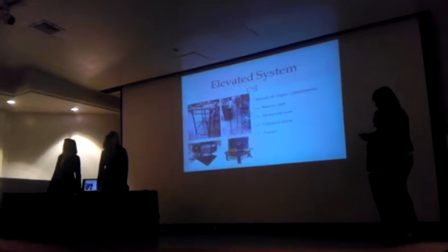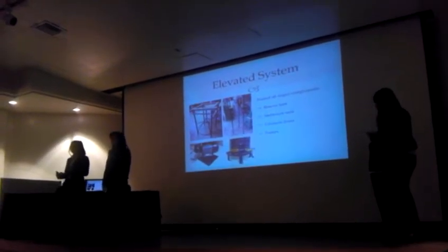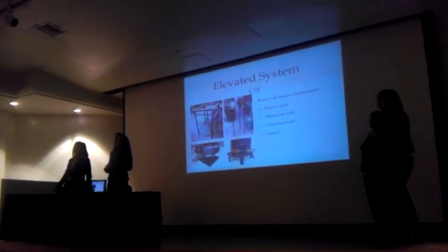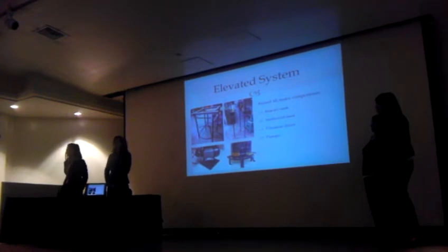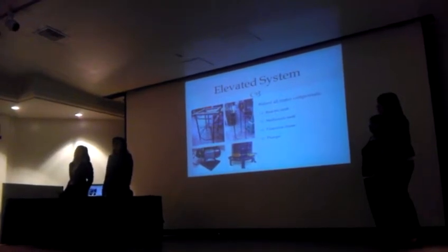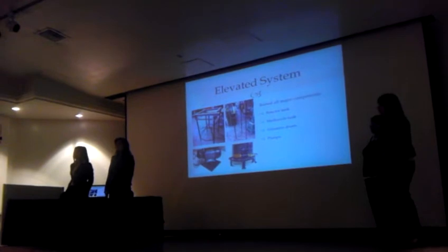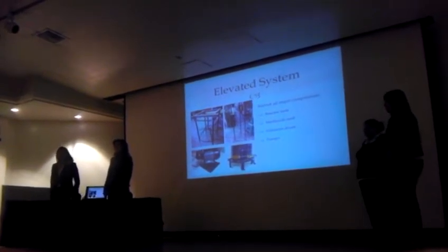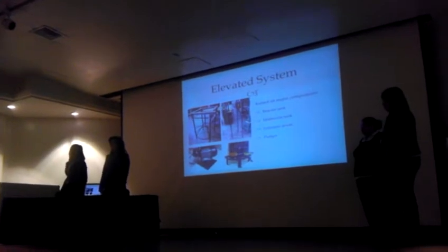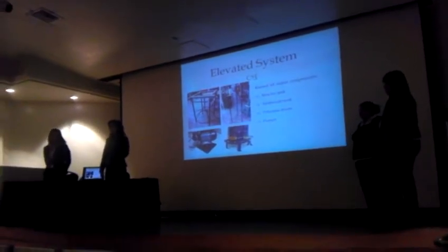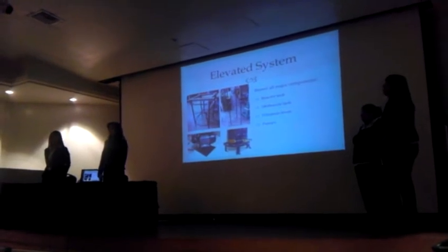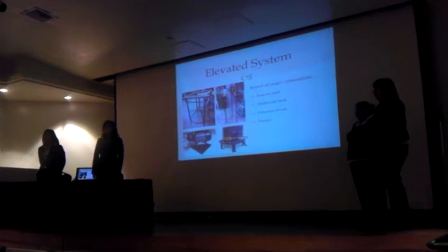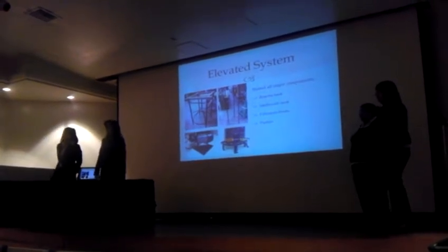Since we had to add all these additional pipings for serviceability, it also changed the height dimension of our entire system. Our reaction tank stand, we had to weld on an additional extension onto it because after we added the fittings, the stand was too short. Our methanol tank we also had to extend. Another part of the system was our pumps. We shouldn't have them sitting on the ground because if something were to spill on them, it's definitely not good for the pump. So we went ahead and made stands for all of our pumps.